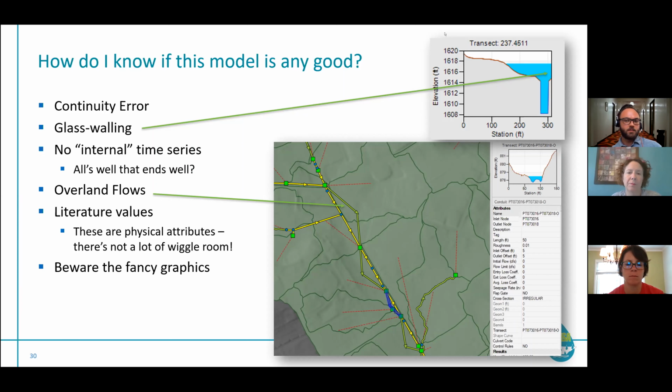Is that a question? Let me see. I actually got a comment: accurate as-builts. Yeah, Don is 100% right. Oh my gosh, how many times have I pulled up as-builts from like the 70s, and I have a microscope essentially on these things. But then I remember, oh, if it's from the 70s, it's NGVD and not NAVD. So what's our factor here? Do we need to adjust this by 0.8 feet or something else?